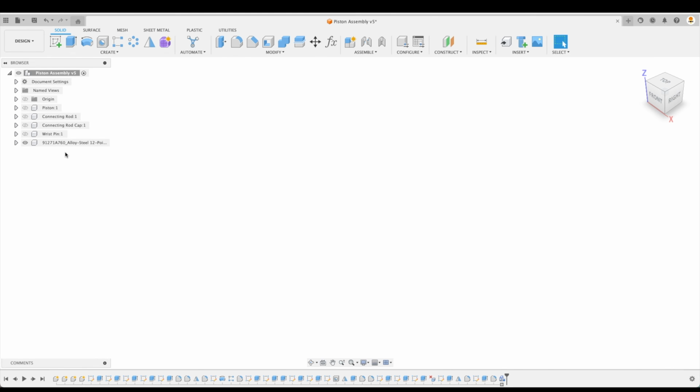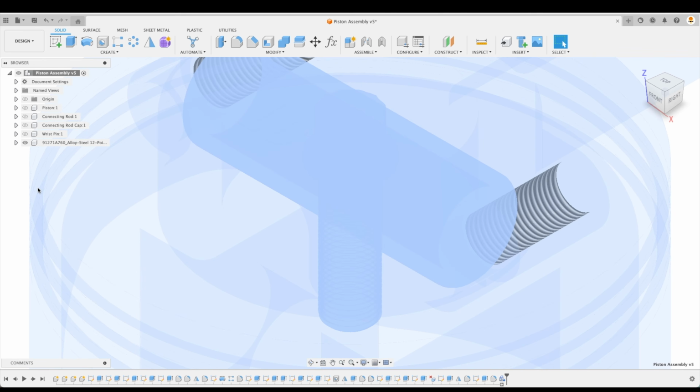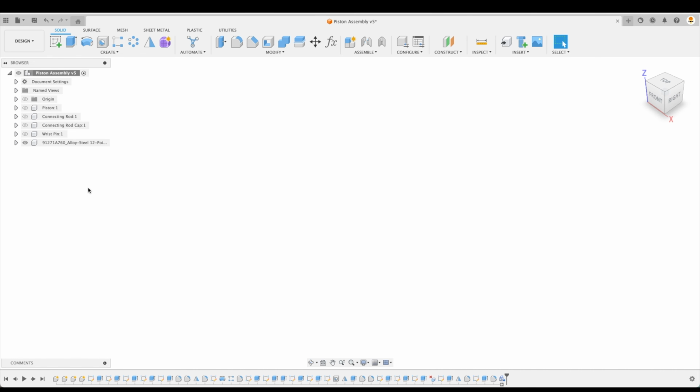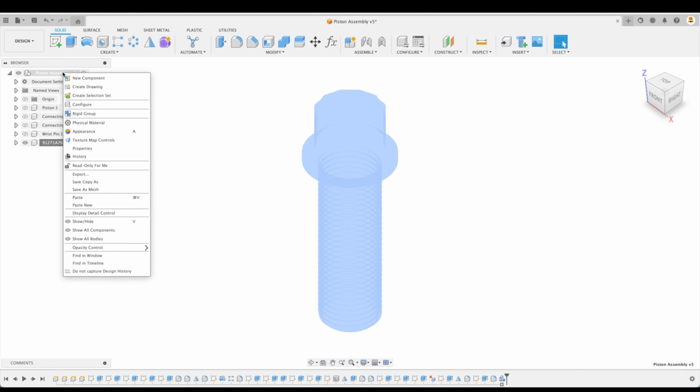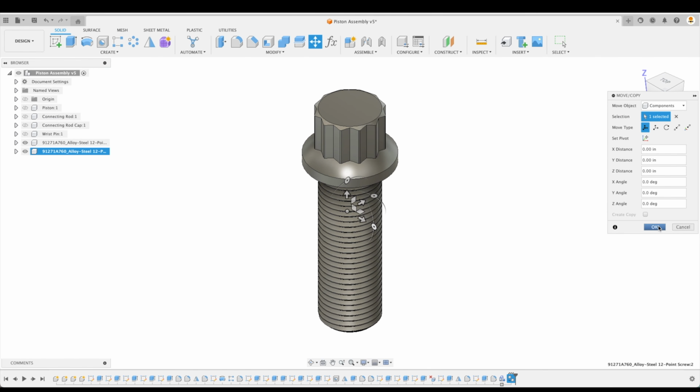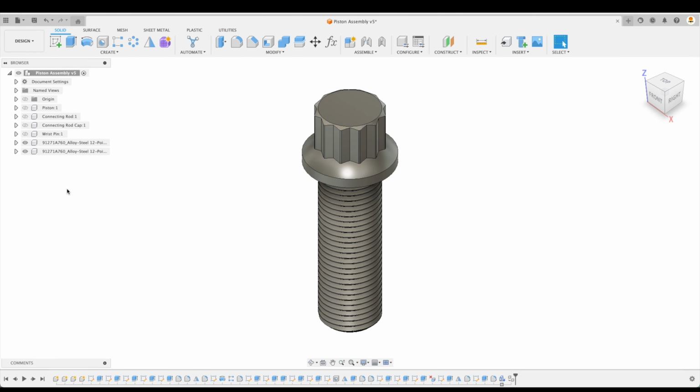Now, we did have an option here. We could have created a new component. We could have called that our screws and then inserted 2 screws into that assembly. But there's a limitation in this, and this is what shows up in our drawing file. When we create a parts list on our drawing, if we've created an assembly, it will simply say that we have 1 screw, even though we have 2. But if we right click and go copy and paste this, it will automatically select it as 1 part item on our drawing, but show that we have a quantity of 2.